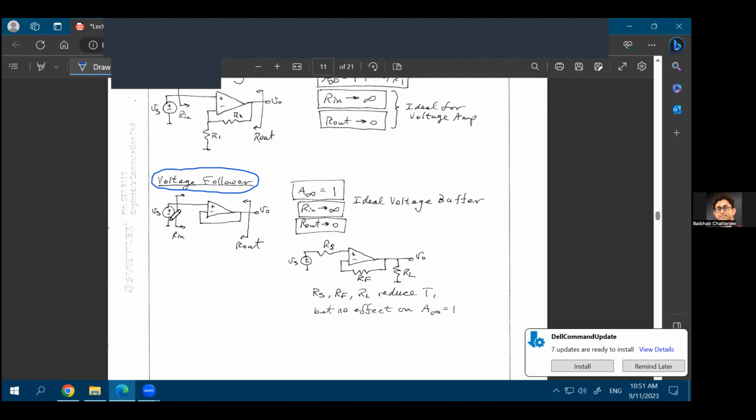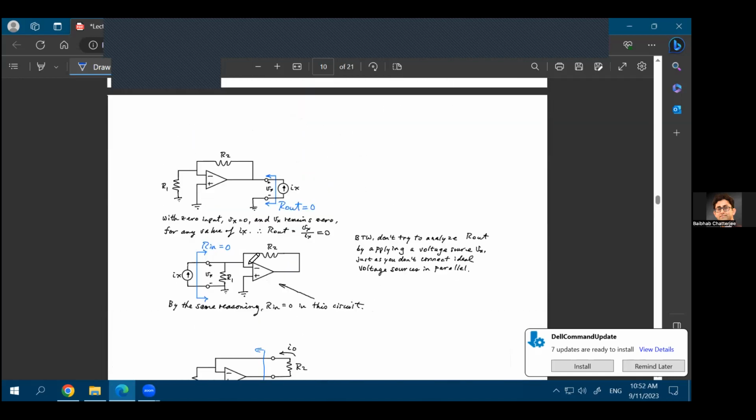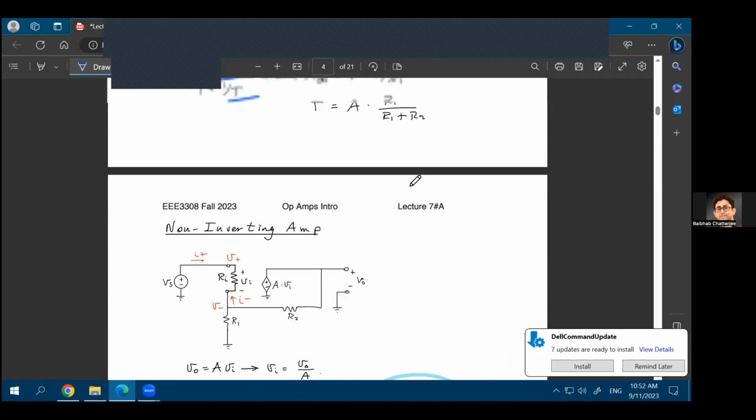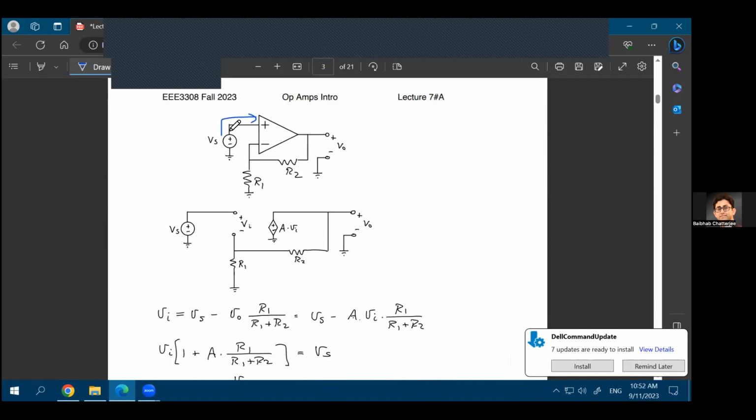Now you already know that this is a non-inverting op-amp configuration because you are applying your input to the non-inverting terminal, right? And you already know that the gain of the non-inverting op-amp configuration is 1 plus R2 over R1, where R2 and R1 were resistances that were present in the previous version of the circuit, which we had just discussed, which was this, that you applied your input to the positive terminal, but you had this voltage division working as the feedback in the original non-inverting op-amp configuration.